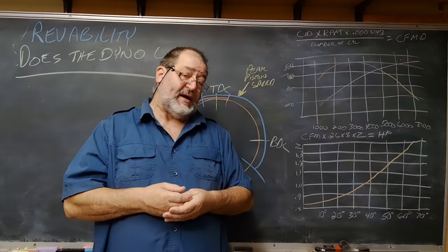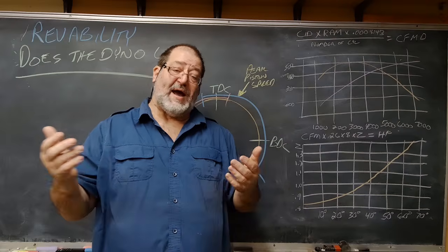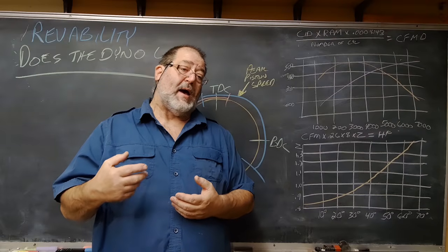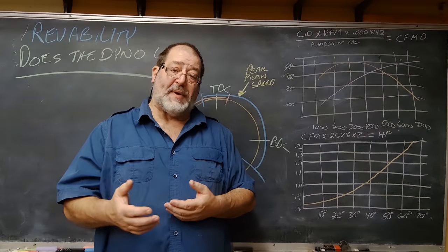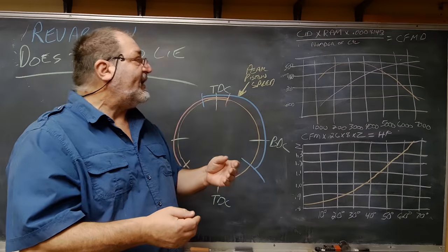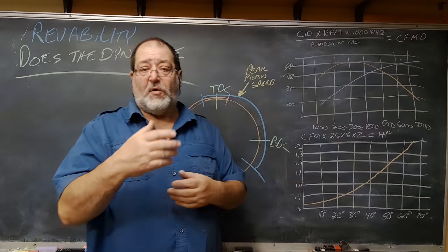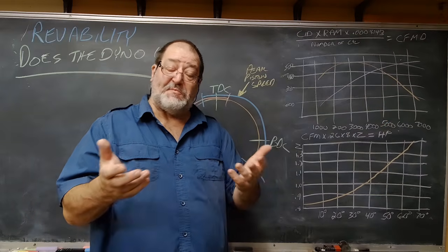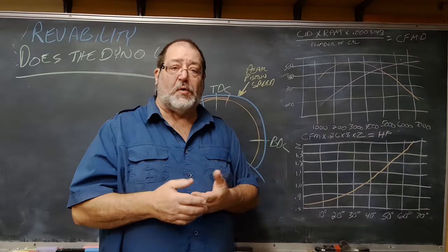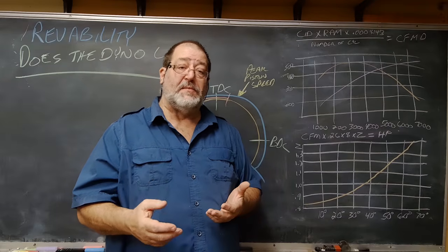Well, technically, when I went to the dyno, and I have the dyno sheet, it was making power up there. But it wasn't peaking there. It was still peaking at like 5,000 RPM. Because even though I'd done a little port work, I had my flow bench at this point, I had a little bigger valve, I had a little bigger cam, I had a little better breathing.